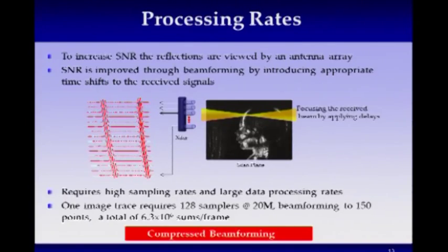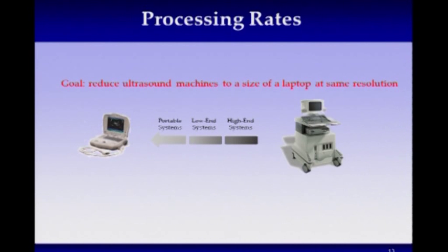And the goal in this project was to see if we could reduce the size of an ultrasound machine. And this is actually interesting, I didn't know this before we started the project, but if you ever wondered why ultrasound machines are so big, there are of course many factors, but one of the main factors is actually the DSP. This beamforming is so complicated that it consumes a lot of heat. They have many processes working in parallel. And today we try to make these chips smaller and smaller, but then you have 3 mechanical fans just sitting in there cooling them all down. That's a little bit absurd, right? We make our chips shrink and shrink, and then you have these 3 fans that just make the machine so big.